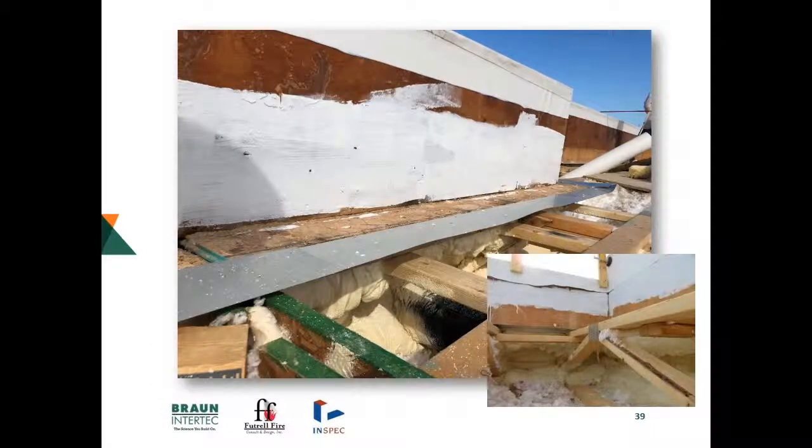Here's a little more of a close-up on the left showing that foam done and tied to the vapor retarder below, coming up and tied to the, we used a Z channel type continuous metal instead of a U channel. It turned out to be a better bend for the contractors and made more sense for installation. The bottom right shows again all that end wall work, all foamed up with a minimum of 3 inches to create that vapor retarder skin that makes it continuous from our wall to our roof.